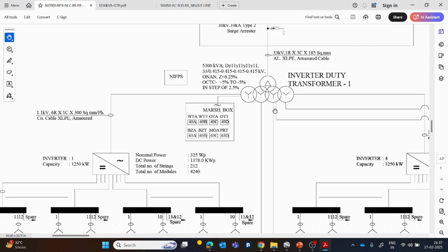And second, in PV the peak generation happens only for 1 or maximum 2 hours in a full day, probably between winter and summer, like February, March, April. There might not be generation during cloudy, rainy, or overcast conditions, or in winter when days are short. So what does that mean?